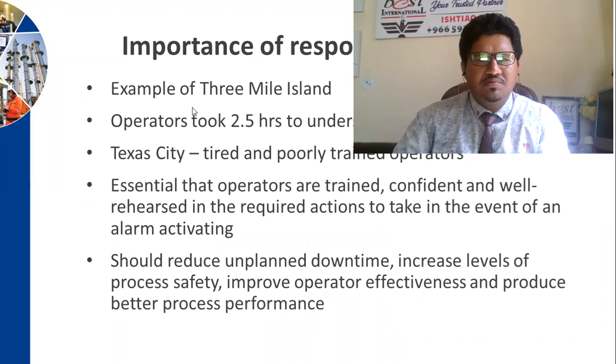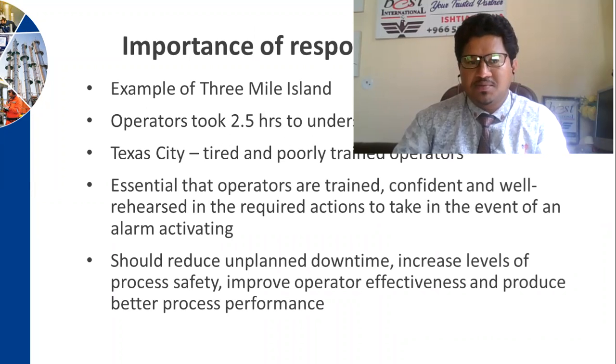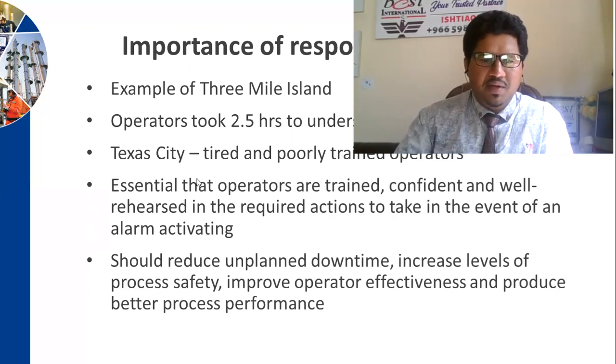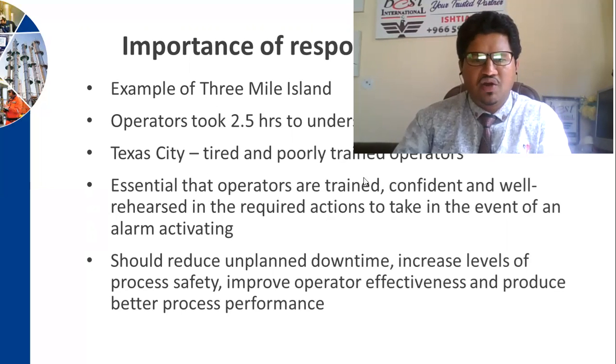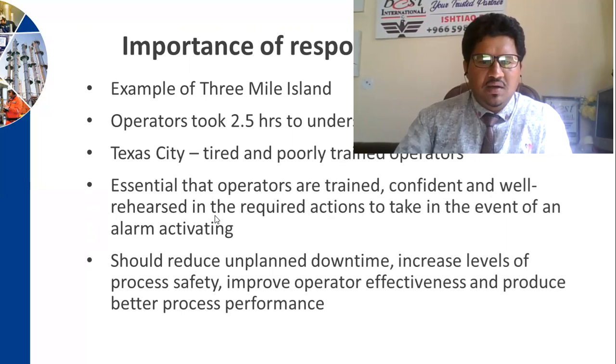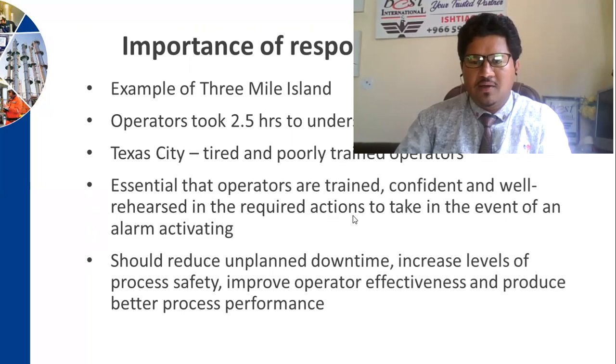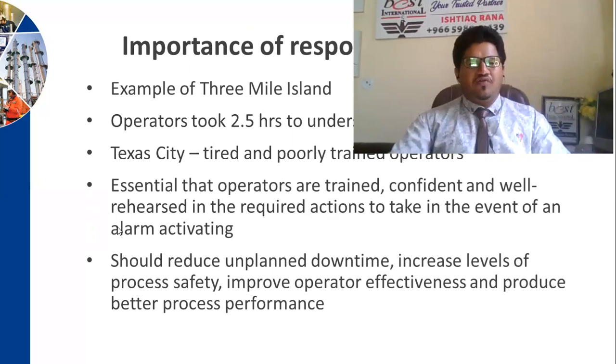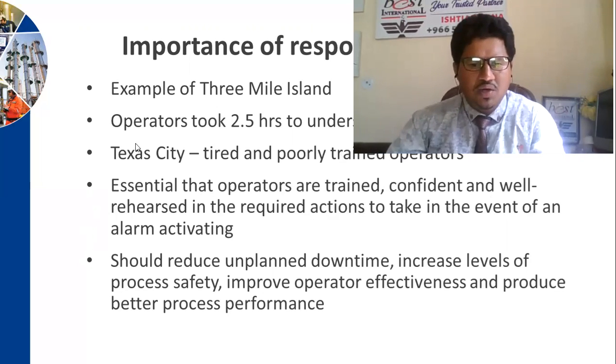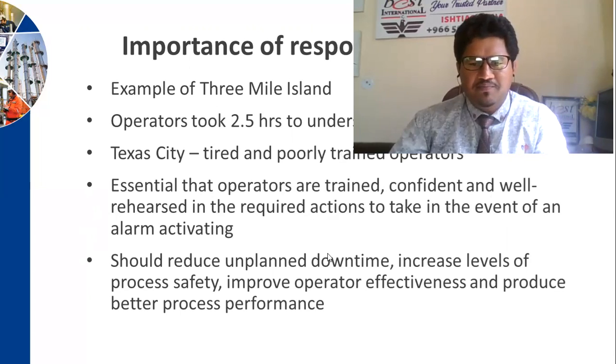Importance of responding to alarms, for example at Three Mile Island, where operators took 2.5 hours to understand the problem. So, responding to alarms is very much important, but sometimes operators take a lot of time to understand the problem, like at Texas City, where tired and poorly trained operators were there. It is essential that operators are trained, confident, and well rehearsed in the required action to take in the event of an alarm activation, and this should also reduce unplanned downtime, decrease levels of process safety incidents, improve operator effectiveness, and give better process performance.